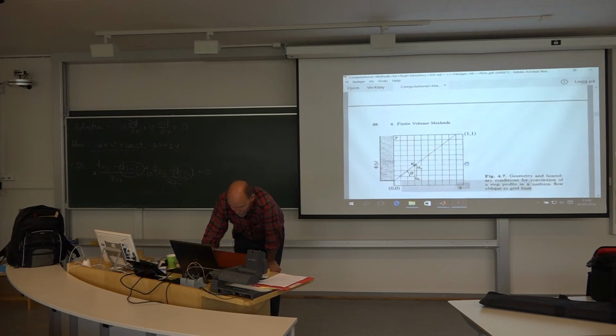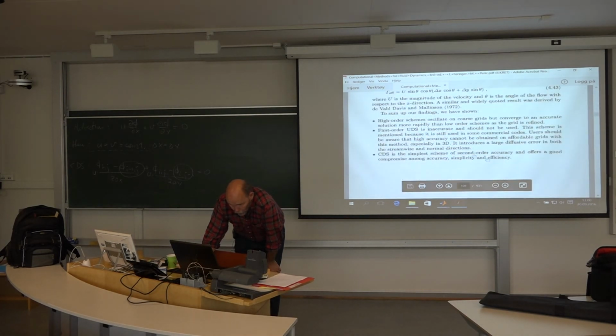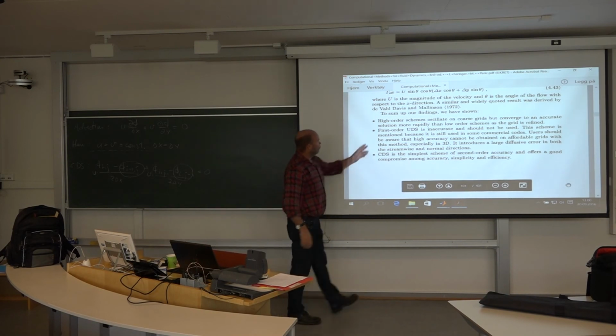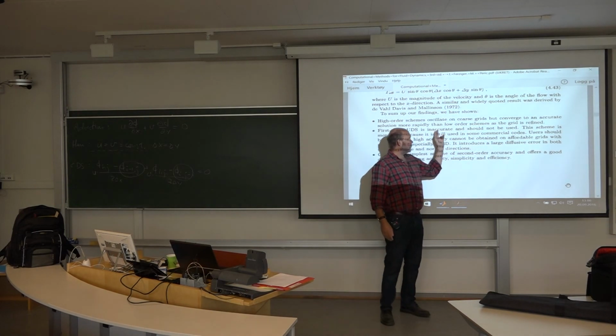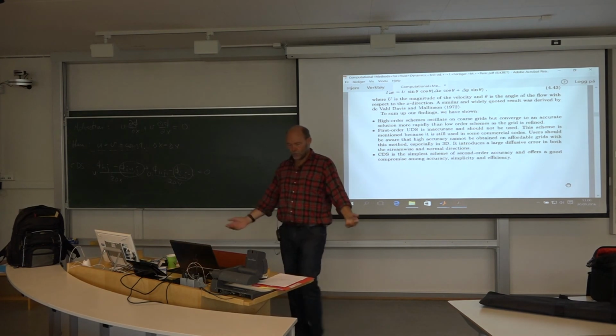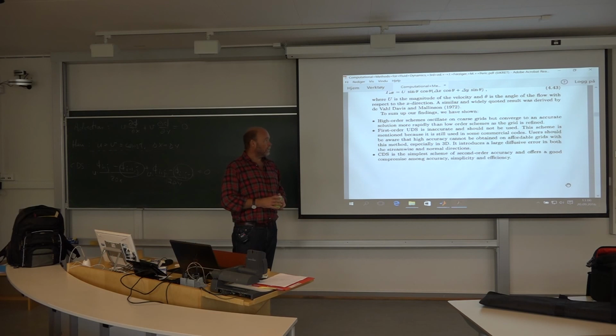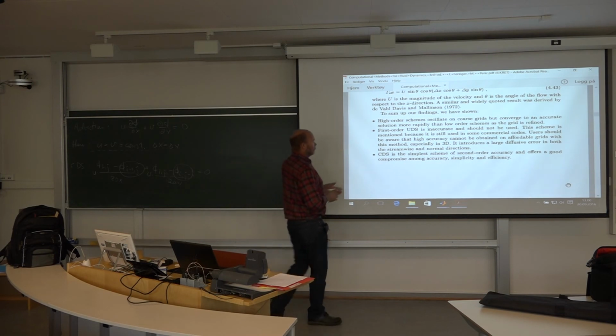So as it says in the book here at the end. First order upwind scheme is inaccurate and should not be used. That's the conclusion. Sometimes we use them anyway. And you risk finding codes where this one is implemented. Maybe they don't like to talk about it. They have just done it without telling anybody because it's so stable. You get a solution quite fast. But the solution is terrible, awful. So should never be used.